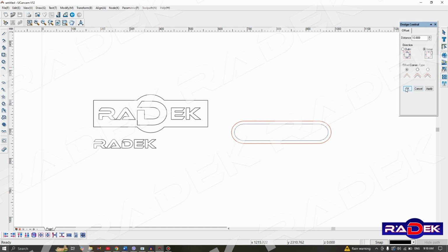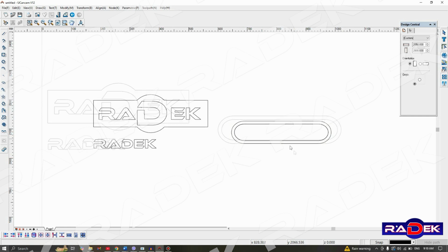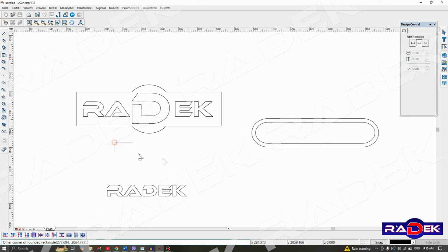What I'm going to do next is to slightly modify our imported DXF file. I need to draw an additional section which will enter the machined region of the stand. I'll start by adding another rectangle and modify its dimensions. I will set its height at 12 millimeters and its length at 150 millimeters.